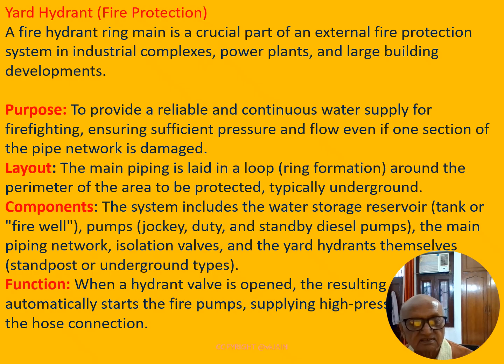The yard hydrants are vertical standpipe type, known as standpost type. When a hydrant valve is opened, the resulting pressure drop automatically starts the fire pump supplying high pressure to the hose connection.